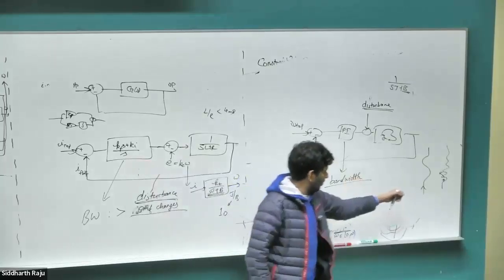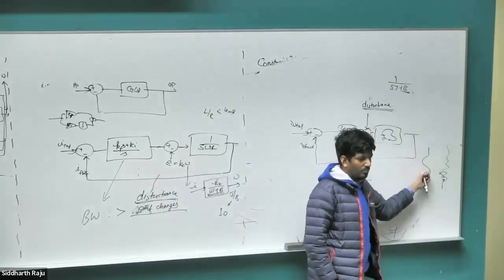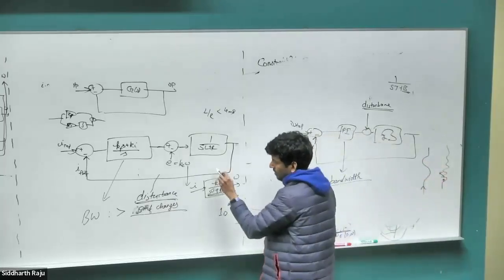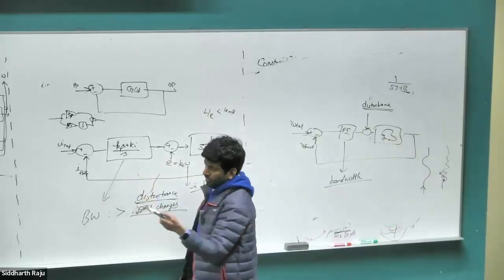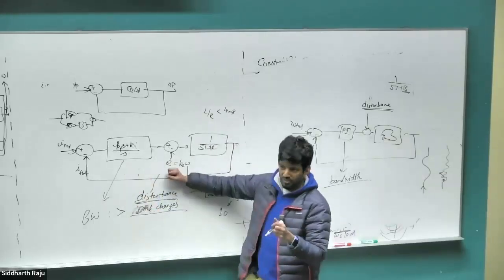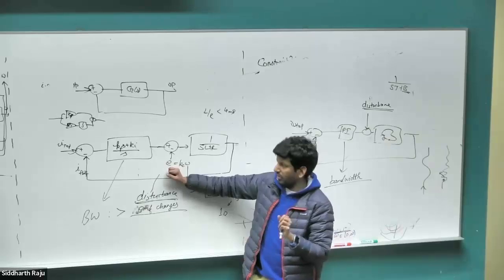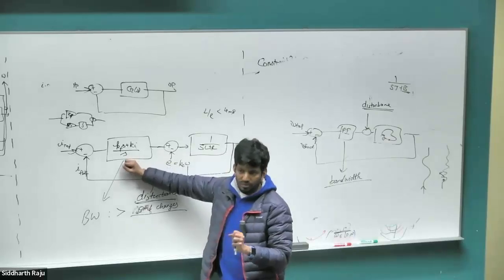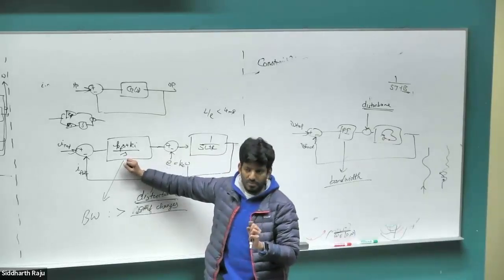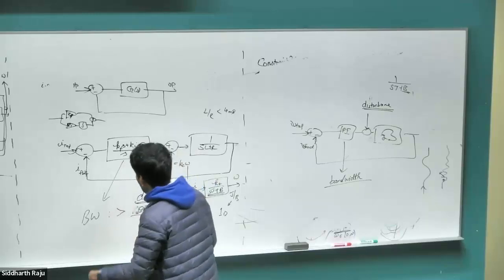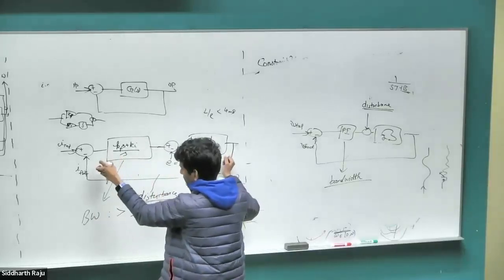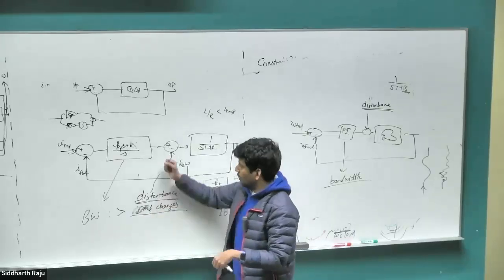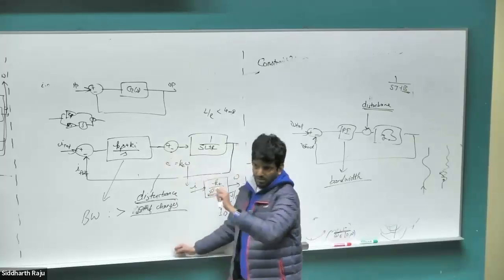Same as how the road is changing quite slowly, we can quite easily process it and become stable and drive comfortably. If it changes too fast, we run into trouble. But that alone is not sufficient. Whatever controller we design also needs to act much faster than the rate at which our speed is going to be changing. Right? So there are two constraints. The first constraint is automatically satisfied for all practical motors. The second constraint is on the controller that we are designing, which we need to make sure happens. When we finish our full control system, we need to ensure that the bandwidth of the system is much, much larger than any rate at which the EMF can change. If it doesn't, then our whole assumption of ignoring this EMF is completely faulty. Right?